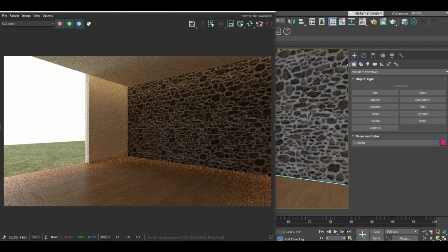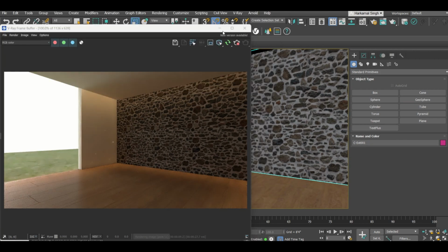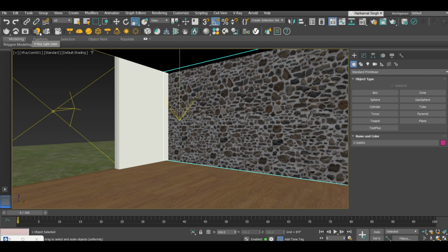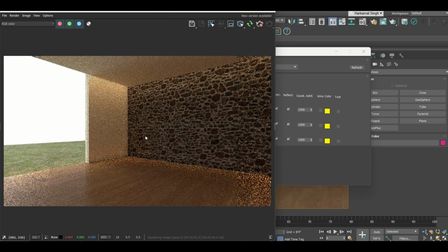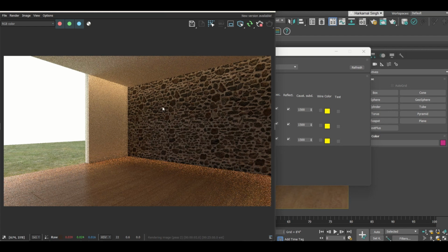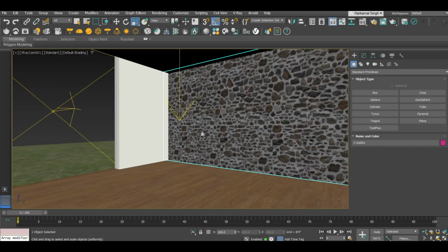Now we need to increase the ceiling light because the reflectivity has been drastically reduced by the texture on the walls. So in this pocket light, make it 100. Now see, there will be a little bit different effect on the room setting, right? So this is how in a different way you can use the square light. Same is the role of disc light, nothing else.